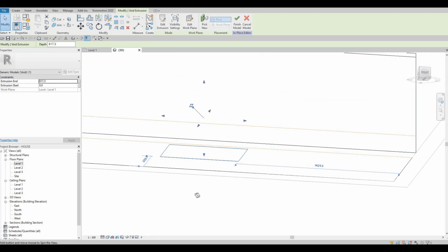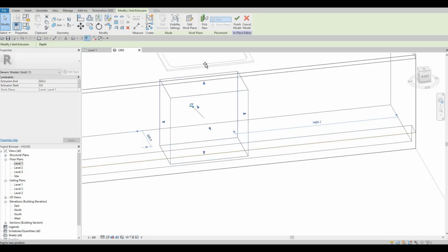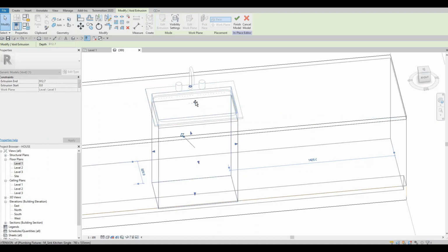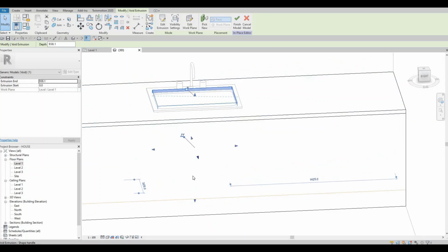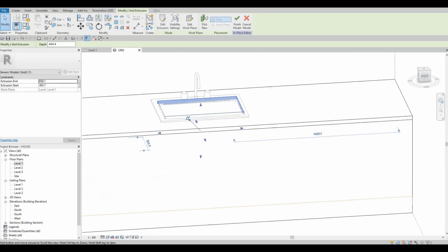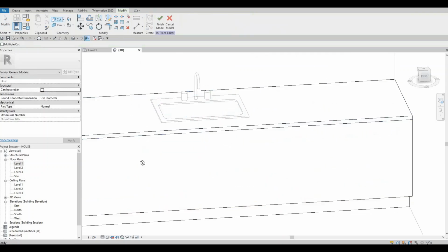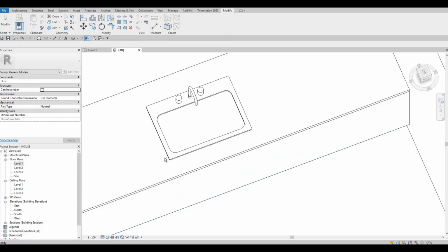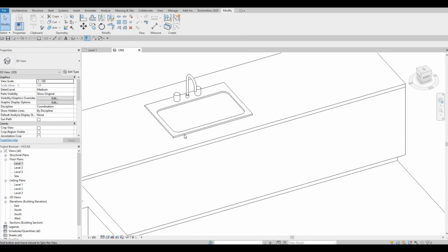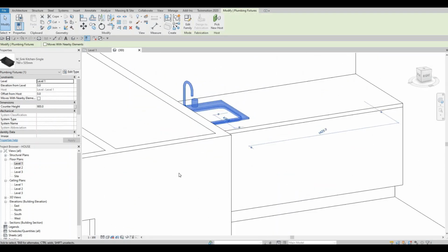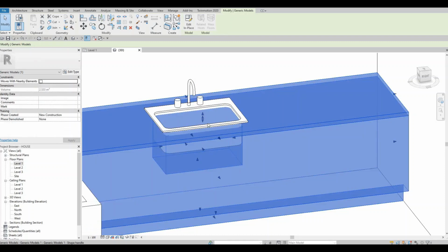Luckily, we haven't added the floors yet. So what I usually do is I'm just going to extend it all the way at the top, and from the bottom just estimate it like that. Then after that, click cut, geometry, and then click finish. So it's still not appearing from what I'm seeing. So let's do it again.